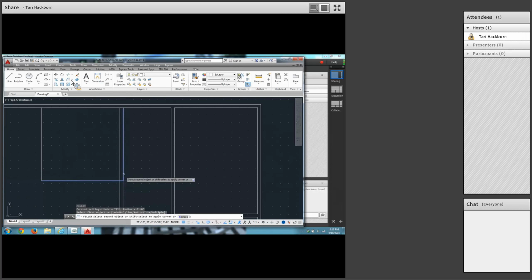Okay. And then we'll offset these two walls 5 inches for the thickness. 5 out this way, 5 out this way, and then I'm going to fillet this corner. If I press enter, it puts me back in fillet, and this corner. All right. And some trimming to do up here. More wall cleanup, right?